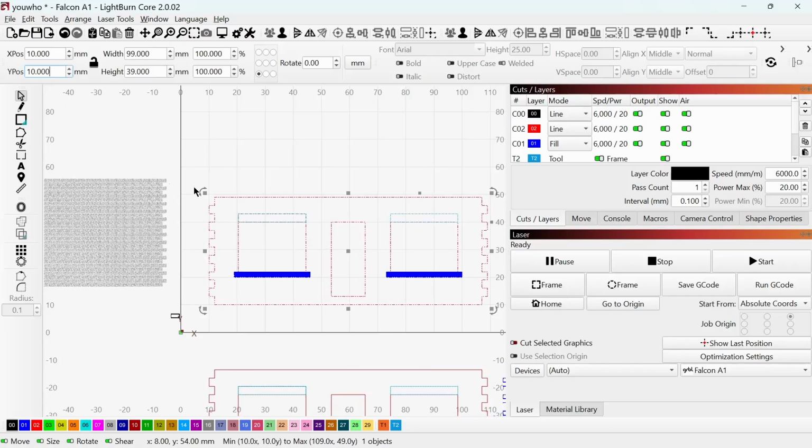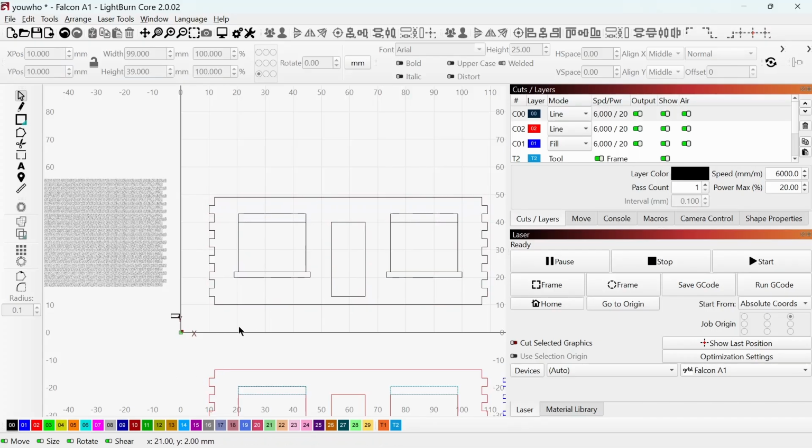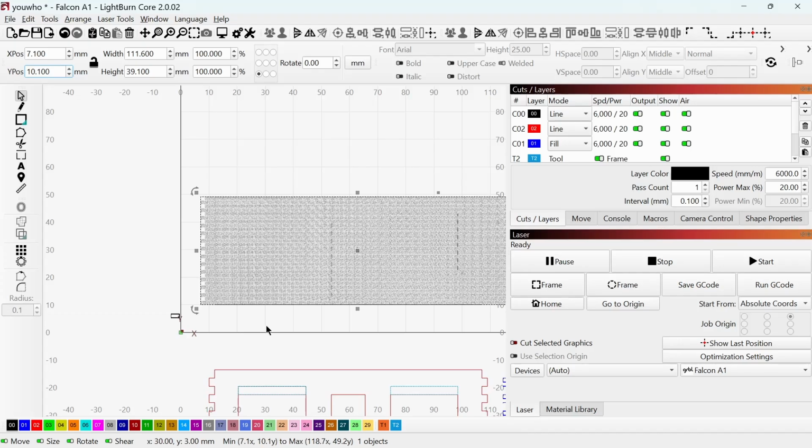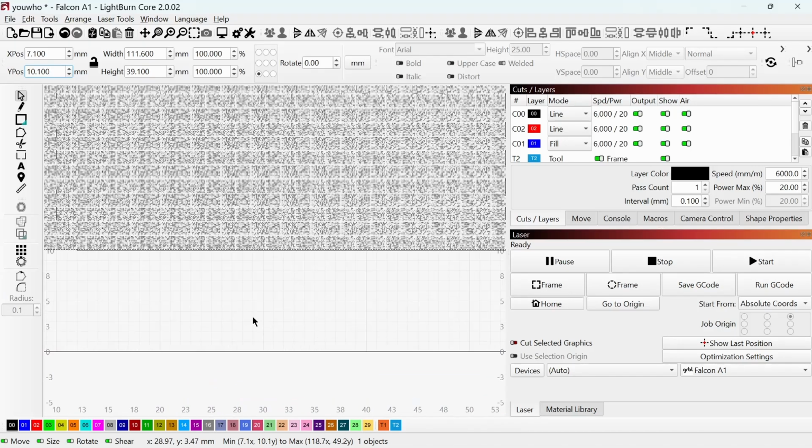Now what I need to do before I can apply this is a mask to the building there. I've got to convert this all to the same layer. Put it back to the line layer. This one here, rather than going to 1010, I'm going to put it to 7.1, tab, Y position 10.1, tab. That gives the room for your brickwork going in place there, folks.